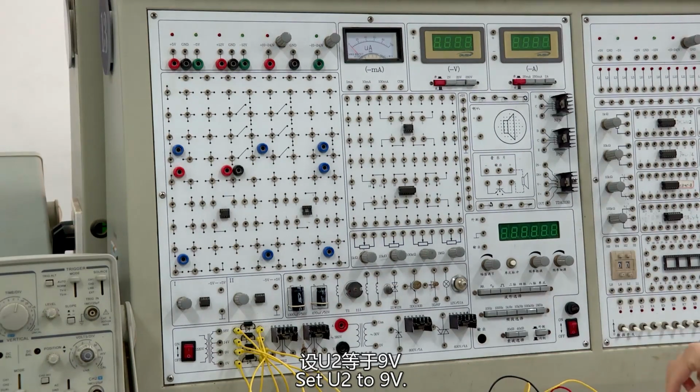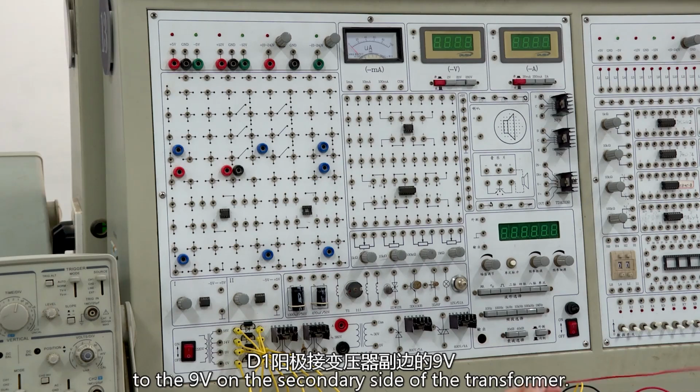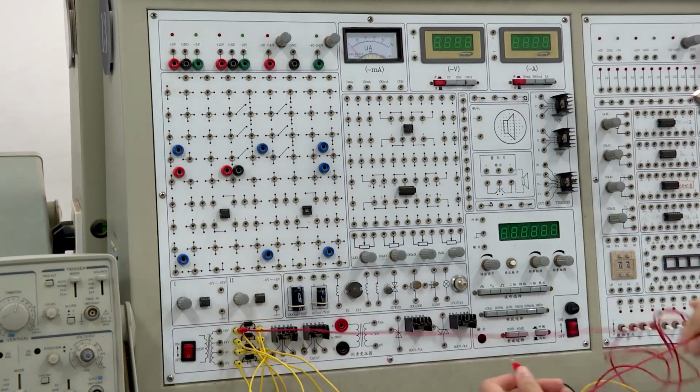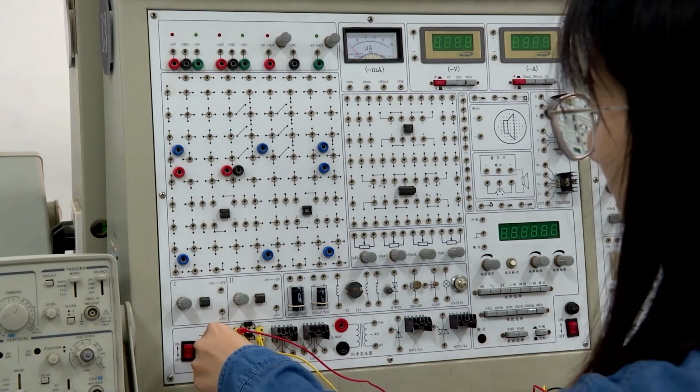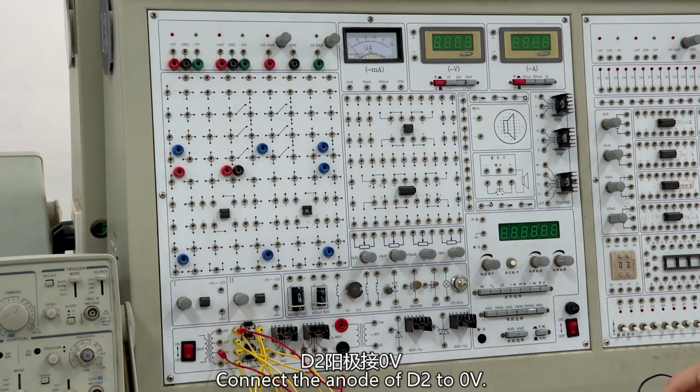Set U2 to 9 volts. Connect the anode of D1 to the 9 volt on the secondary side of the transformer. Connect the anode of D2 to 0 volt.